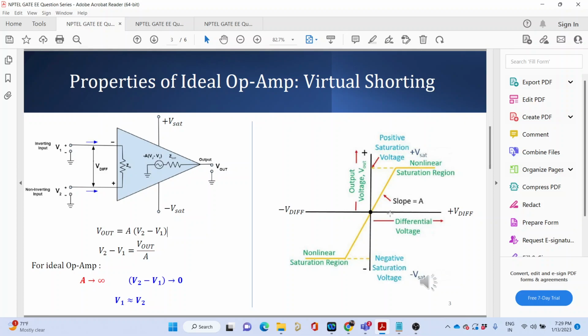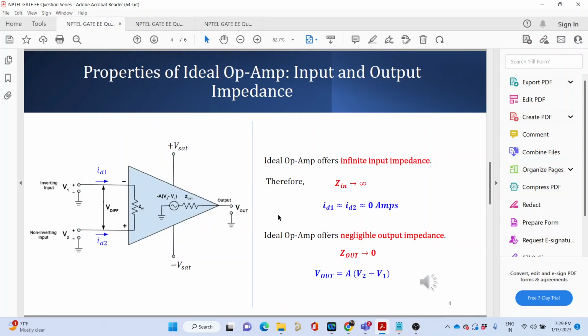There are controllers where we use this PI controller. There is a problem with PI controller, which I have already told maybe in the previous session. So there is something called anti-windup. Okay, the capacitor saturates and it remains in saturation region. So there is a problem with that configuration with the PI controllers. So this is something that you have to keep in mind while you analyze this kind of op amp circuit.